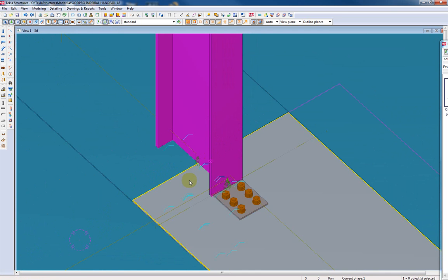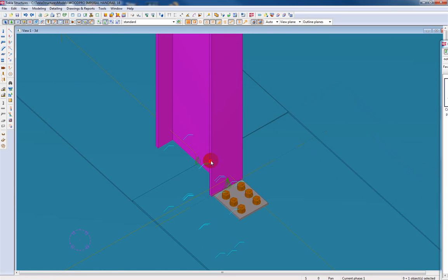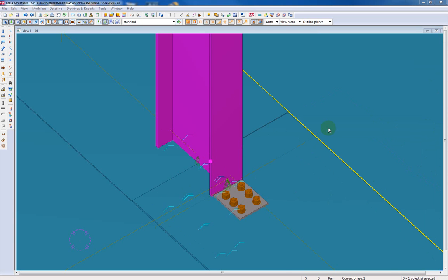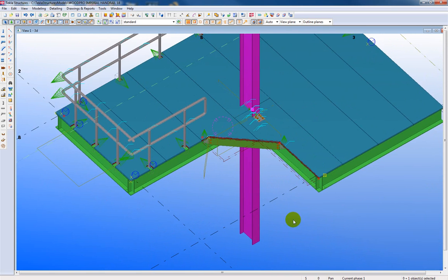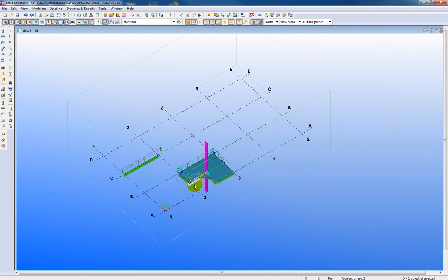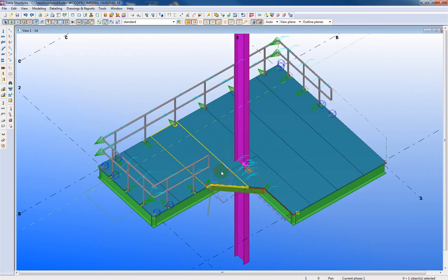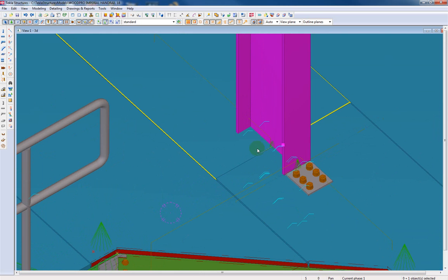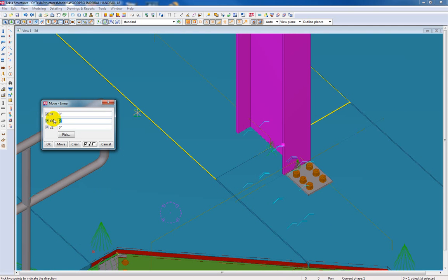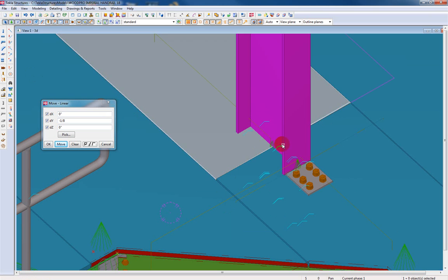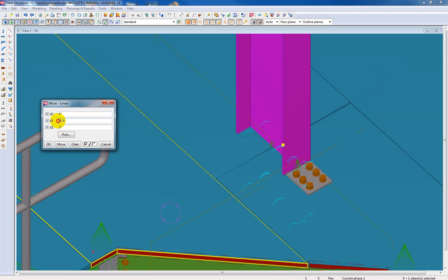Of course, what we would do is take this handle here and move it in the, let me see what direction we would move that in. Probably that is going to be in the -y direction. So I would move that in the -y, -1/8, like so. And then on this one, I would move its point +1/8. And there I have my 1/4 inch gap.